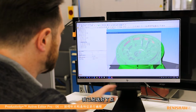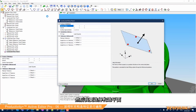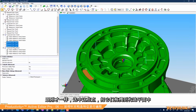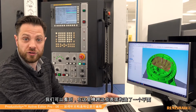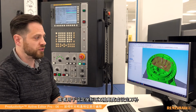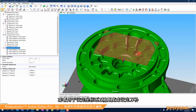So I've selected my points. I'm then going to choose constructed plane. Once again, select those points, drag them onto the plane. And we can see here, that's the plane that's now been constructed across those surfaces. And again, that can be used for a rotation, maybe to level an axis, or set a Z height for your coordinate system or tool offset.